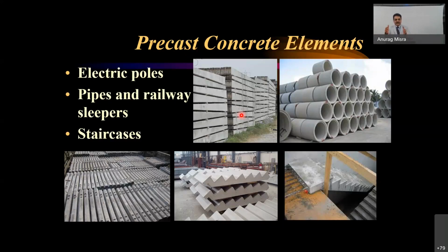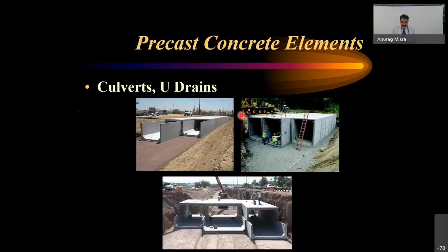Once the concreting is over, next day take it to the curing chamber, and depending on what strength you are looking for, maybe 36 hours to maybe a week, you are done with that. Beams, the same way. You could create beams, and wherever you want a beam-slab connection, you leave the stirrups on top without casting. Pre-casting is done, and then the stitch concrete, a very little amount, can be done on site. That is how the connections are made at site.